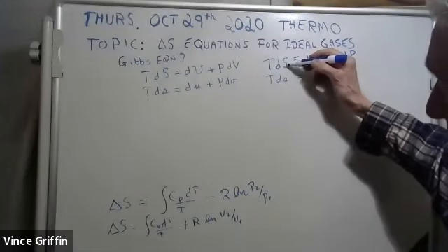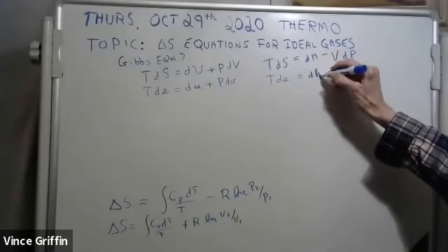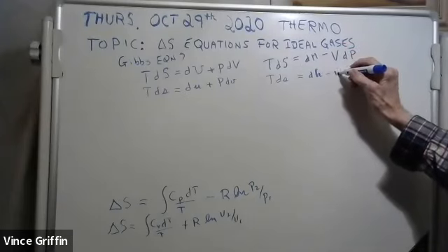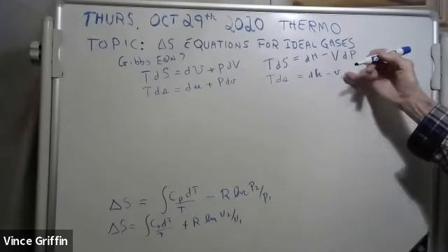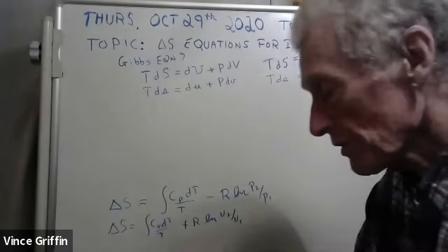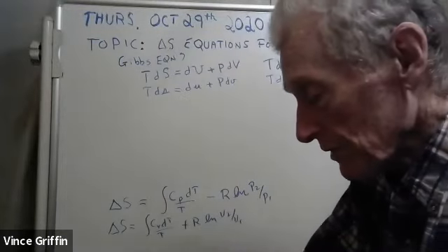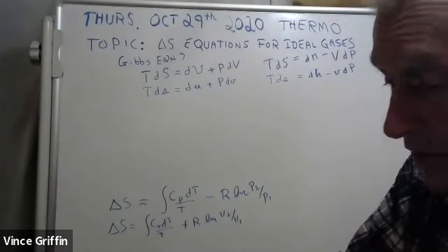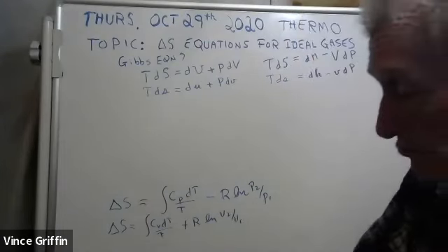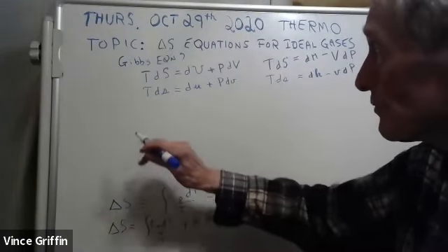See, this is entropy, and this is specific entropy. This is enthalpy, and this is specific enthalpy. This is volume, and that's specific volume. Those are your Gibbs equations written in little letters. Those equations are good whether you have an ideal gas or not. They're good for refrigerants, ammonia, water, you name it. They're good for anything. Now, where did they come from?